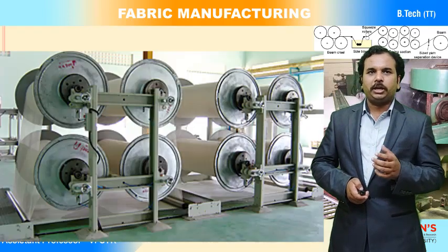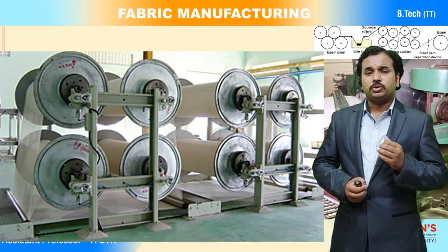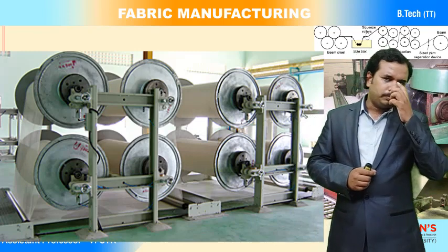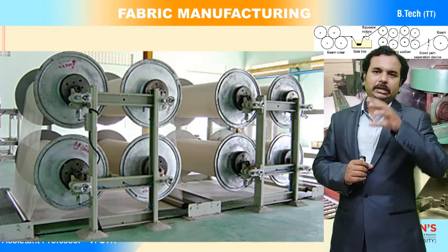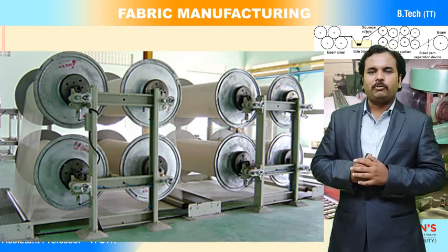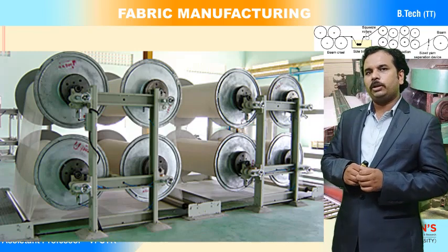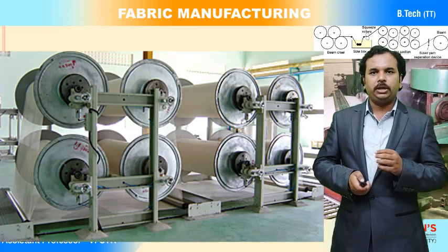Then you can observe a clear picture again of the vertical creels. In most cases, industries follow the bottom withdrawal, because with the top withdrawal there is fluff and dust accumulation at the top side. Mounting, or passing the warp sheet through the several rollers or guide rollers, is somehow difficult. That is why bottom withdrawal is generally preferable, and this is how the warp beams look.